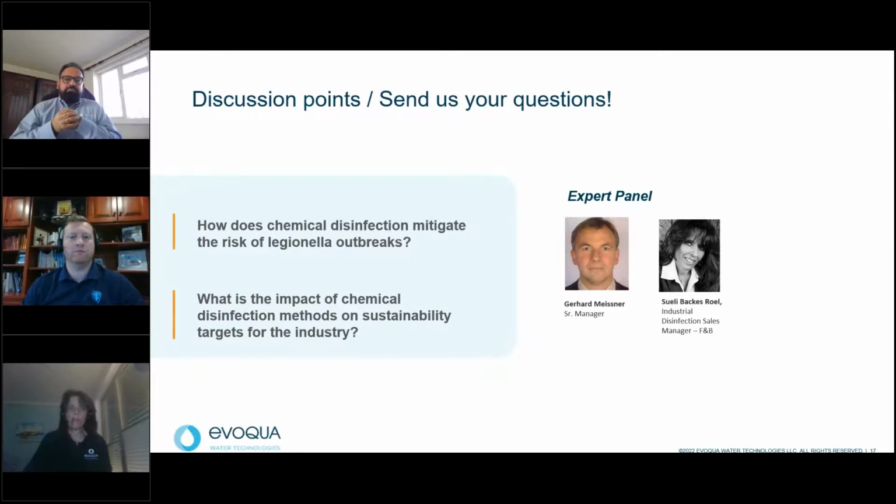Therefore, a sustainable disinfection approach providing a deposit effect is essential, and this can only be provided, according to our experience, by chemical disinfection with a strong effect towards the biofilm, which is on the one hand removed and on the other hand avoided to reform. Such an effect especially applies for chlorine dioxide disinfection because of the specific dissolved gas character of chlorine dioxide.